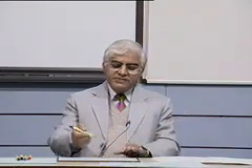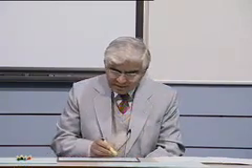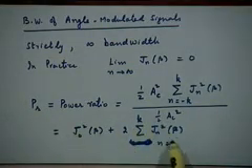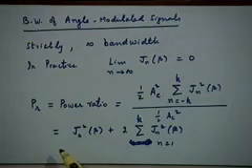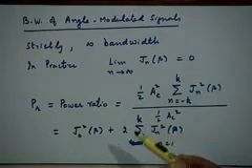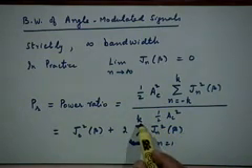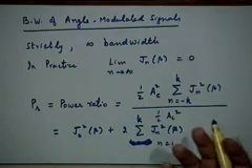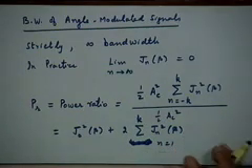That means the value of this power ratio is 0.98. So basically what you need to figure out is for what value of k this turns out to be about 0.98, because this ratio can at most be 1. So the value of k for which this becomes about 0.98 would be the 98% bandwidth of this signal.